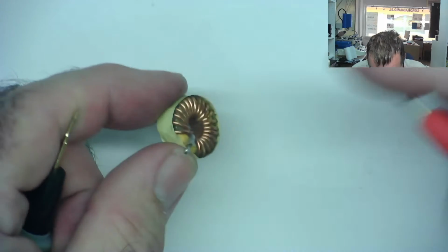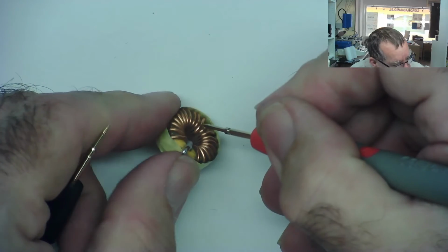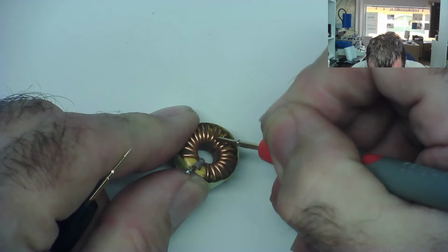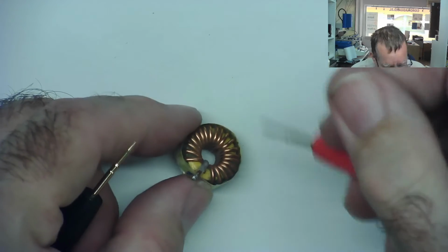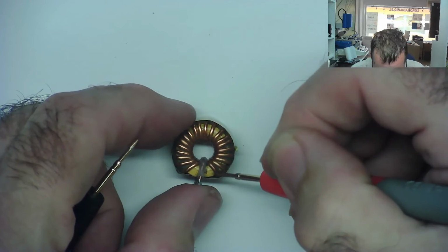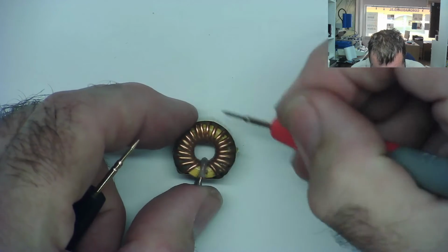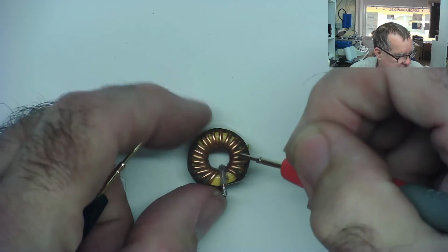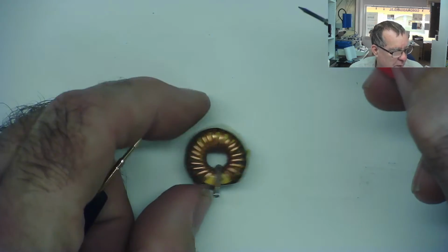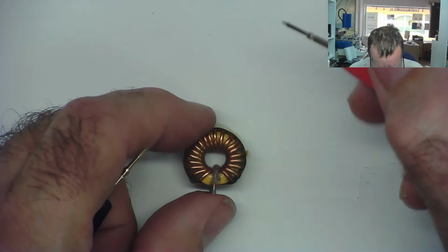But it's possible for that insulation to get broken, usually again down to some sort of physical shock, and for two wires, two turns, to touch together. Now you might think, well, let's look at this piece of wire here. There's, I haven't counted them, 24 turns, 25 turns maybe. So if two touch together, you've now got 24 turns, so that wouldn't make any great deal of difference.